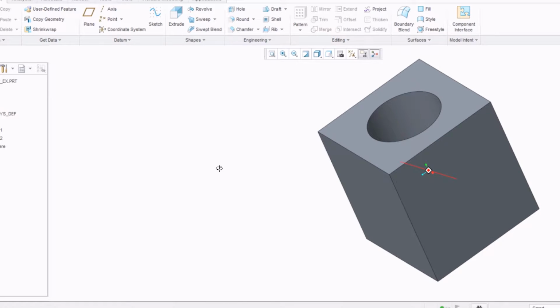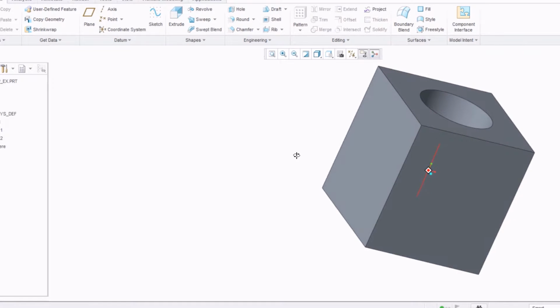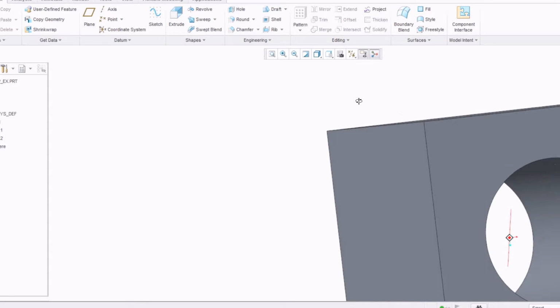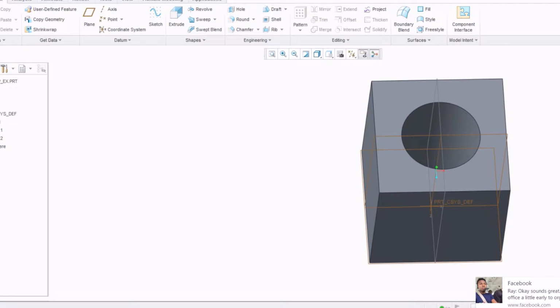I guess while I'm here, I'll show you really quickly how to make the rounds and the chamfers. So these are very important features, especially in engineering design, as you learn from your solid mechanics and also materials classes, that sharp corners increase the total strength of a force and can have the effect of propagating a crack. I know at Lockheed Martin, they tell us all the time, make sure you round your corners. It really puts us in a lot of trouble when you have these sharp corners, especially on parts that have a large force applied to them or under high amount of stress.